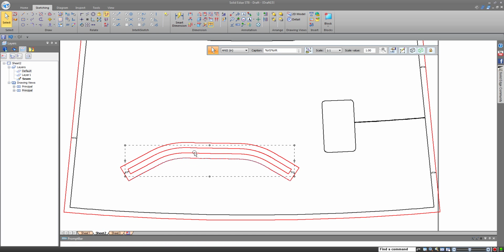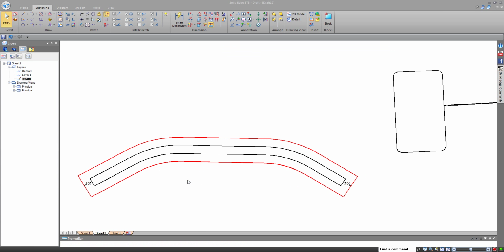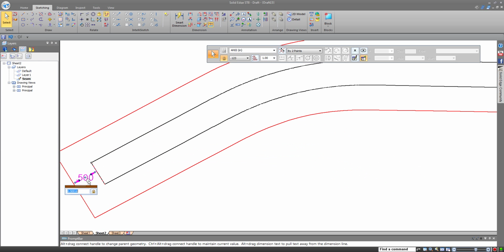And I can tell you why, because this is actually a spline profile. When I offset it, you notice it creates a spline with a whole bunch of points. So when you send this out as a DXF to your burn machine or laser, it's going to see all these points go crazy. Right click, simplify, and say OK. Doesn't change the curve. It actually just changes the slight tolerance and gets rid of all those extra little points. Makes the file a lot smaller to deal with and a lot easier for your machines to read.